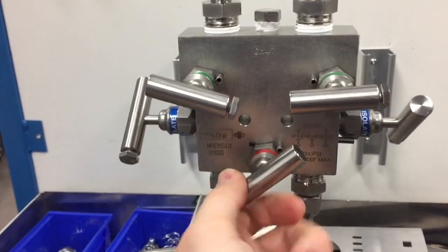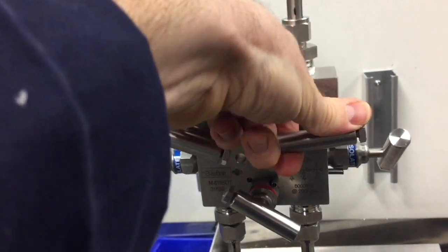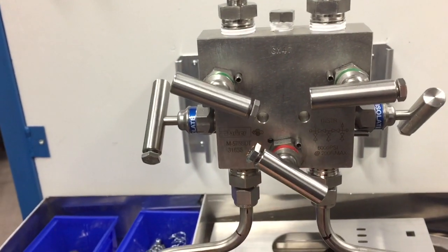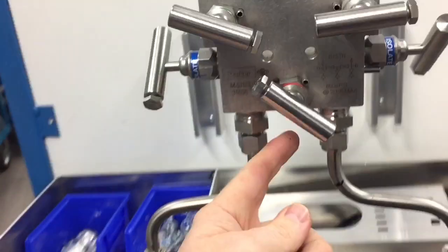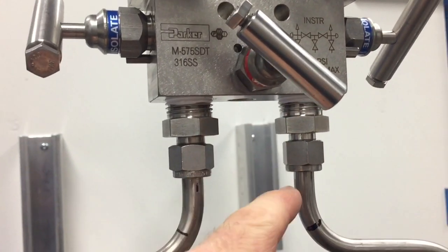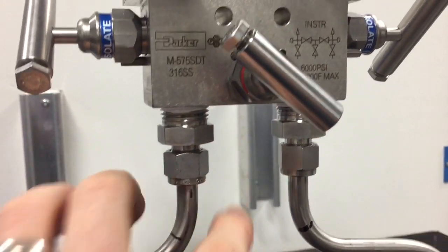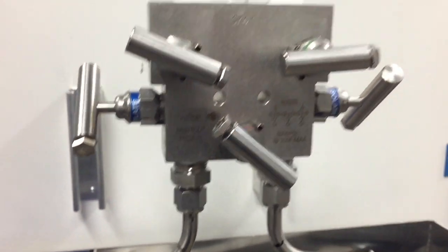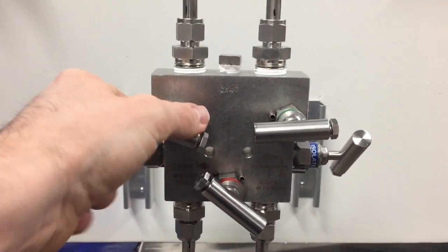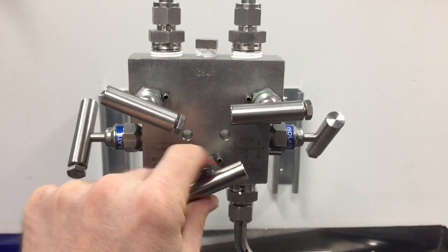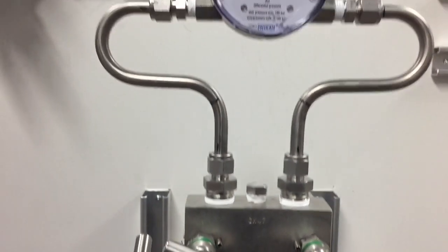And then normally we leave the vent open, so that if one of the equalizer valves is leaking, since it's instrument air here and we just have this vented to the room, we could hear that there's a leak. But sometimes if this gas is toxic or isn't air and can't be vented into the room, there'll be a line connected into here so that it is run to either flare or somewhere where it can be disposed of properly. So during normal operation: equalizer valve shut, vent open, and isolation valves open.